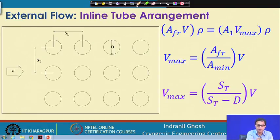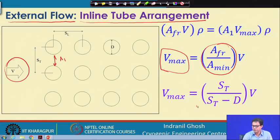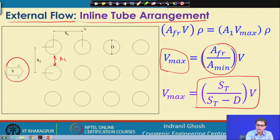Now, we are talking about external flow, and this is the inline arrangement of the tubes, where V is the velocity and we have estimated this V_max to be the frontal area divided by the minimum area A_1, and finally it will be given by S_t by (S_t minus d) into velocity. So, this is for the inline arrangement of the tubes.